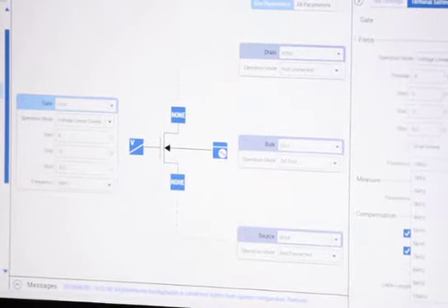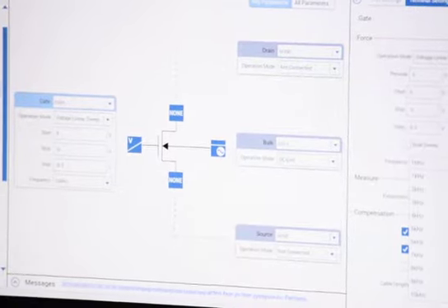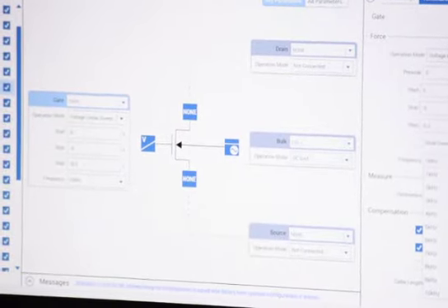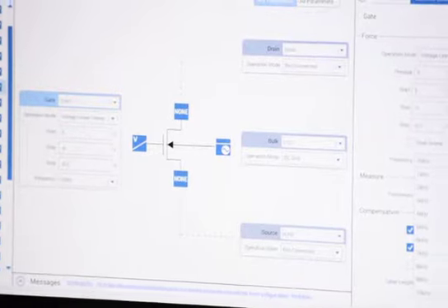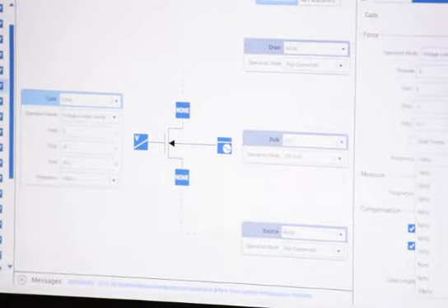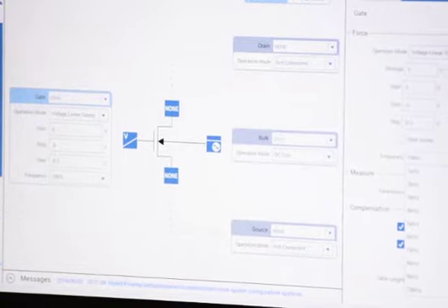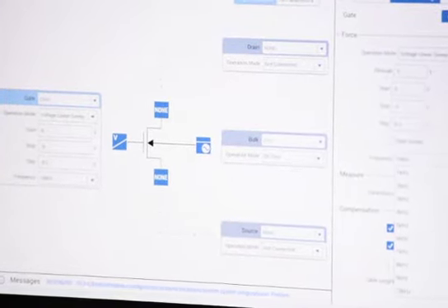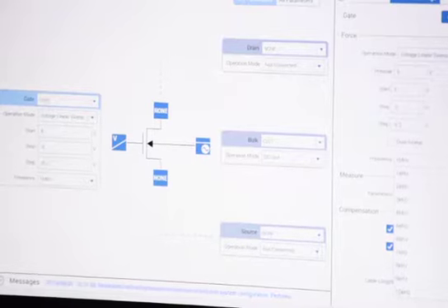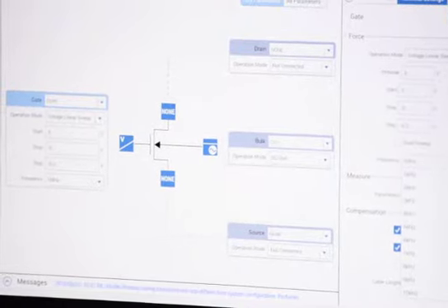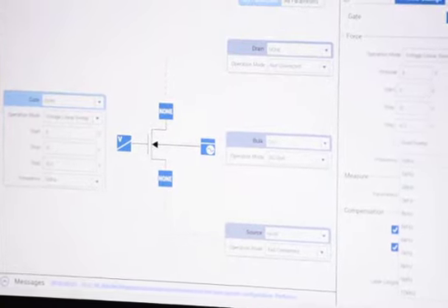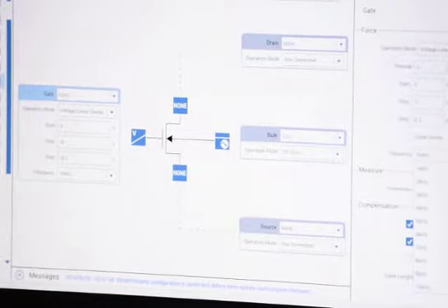How far is it off? It's off from a time standpoint. It's supposed to be calibrated once a year. It's telling me that it's beyond its calibration date. I don't know if the calibration's off at all. It may not be, but it needs to be checked. So before you publish any papers, you should probably make sure that it's calibrated. But if it's just over a year, if you do the femtoamp measurement, then I might see a problem. But what if you do a nanoamp or something? How bad does it get?